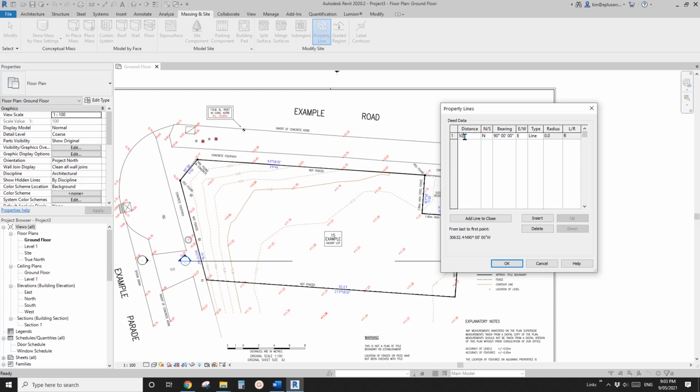Okay, so let's try again. For example, 50 feet and 3 inch. So click. So that's millimeter, become millimeter. And also you can type in meters as well. So for example, 100 meter. You don't need to type another 30 because sometimes too many zeros. So you just type in m. This meter will convert into millimeter. Okay, so 10 meter. That's it.